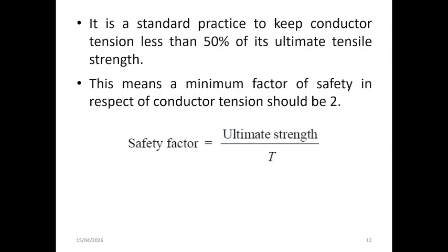So this concept can be expressed through the safety factor, which is defined as the ratio of the ultimate tensile strength of the conductor to its working tension, as you can see in this equation. So safety factor is equal to ultimate strength divided by tension.